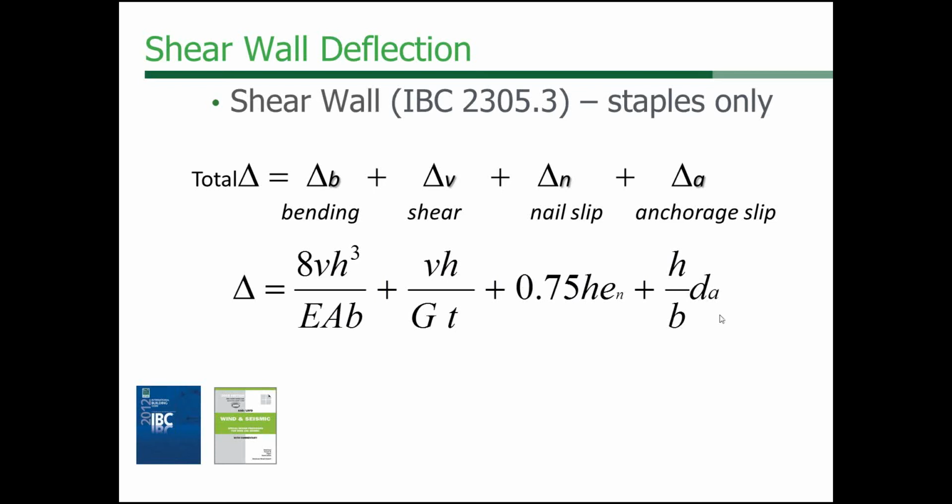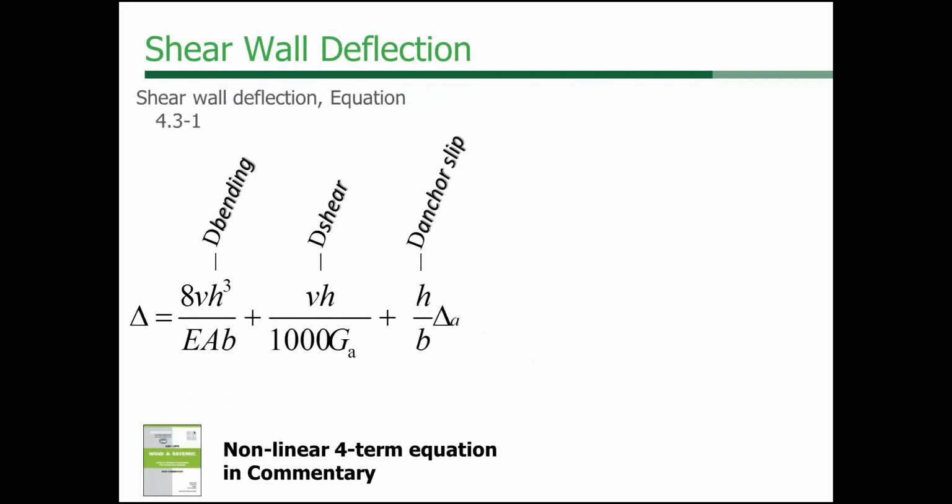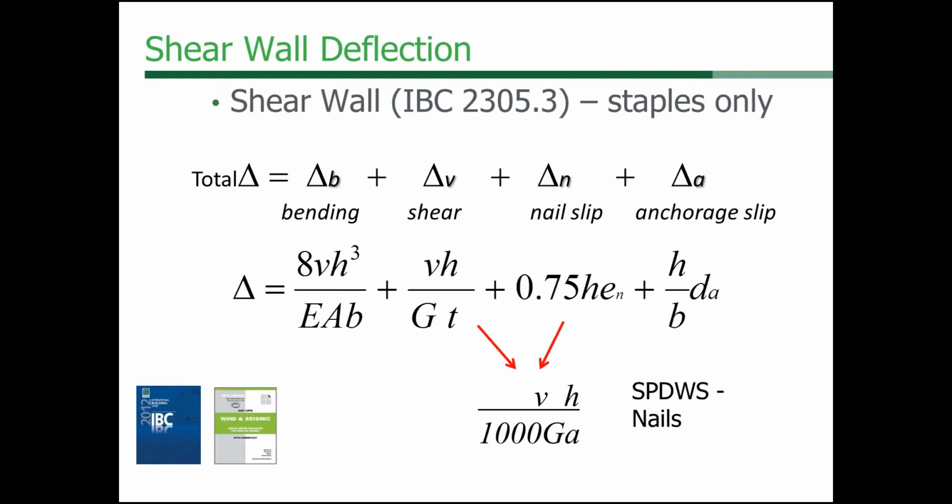And for those of you doing mid-rise construction, if you're using continuous tie rods, your rod elongation, shrinkage compensators, and crushing will play into this fourth term. Well, in the wind and seismic provisions, we combined the middle terms to make it a 3-term equation right here.